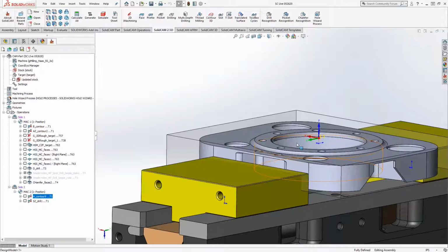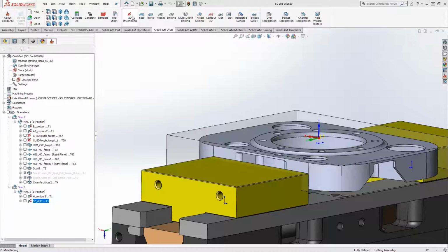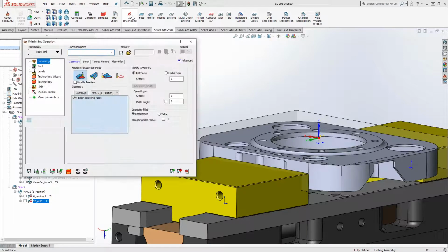So Scott's question: does SolidCAM have its own macros, or does it use Renishaw installed macros? That I'm not sure of. Kevin, do you know? Yeah, that's going to be all pulled off of the Renishaw macros. So like probe web, probe X, Y, Z, those are all going to be your Renishaw. Now, if you're not using Renishaw, then it would be set up custom macros.